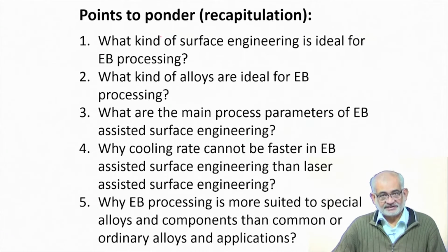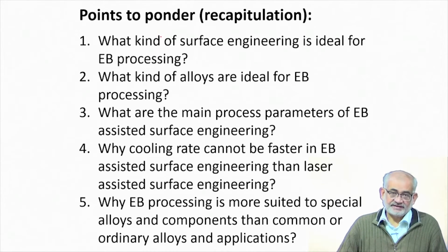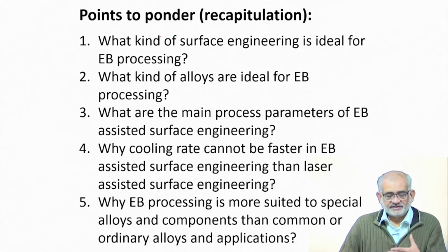So that's a limitation. But at the same time it should be argued that laser or many other processes actually are done in air. So if you are dealing with zircaloy or zirconium or titanium, which are very highly reactive ones, then EB is better suited than other processes.